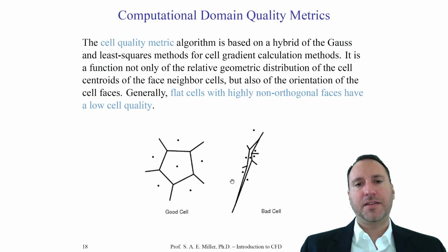Today, a lot of this is done automatically, so you don't have to go in and manually fix these cells. But if you're generating a mesh of billions of cells over, say, a landing gear of an aircraft, which is very complicated, then you might encounter bad cells created automatically by the grid generation program. You'll have to go in and tell the solver to try and fix them automatically after it identifies them through statistics of different types, or go in and manually adjust them yourself. For example, in this bad cell, I could collapse this inner volume or element by connecting nodes and merging the nodes here and here to improve the metric.